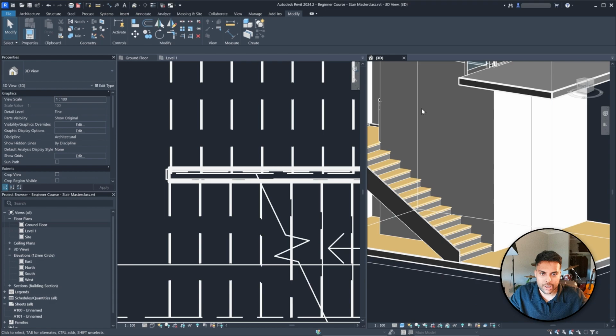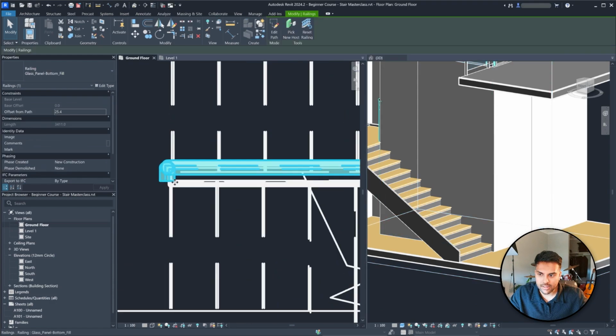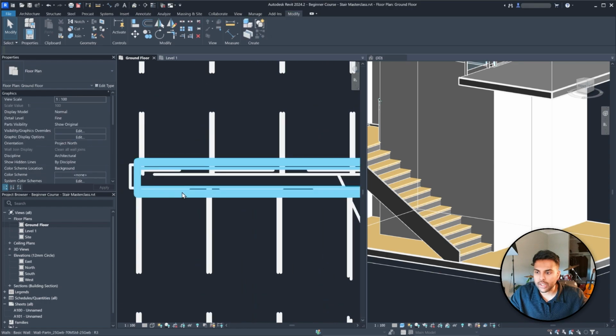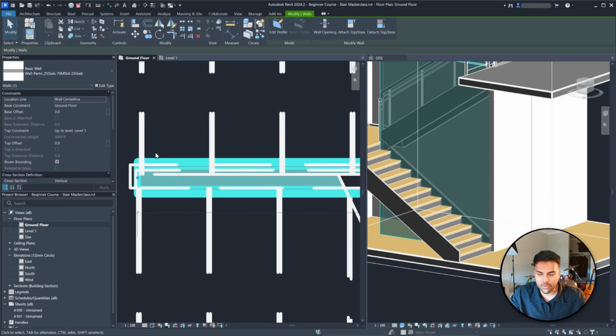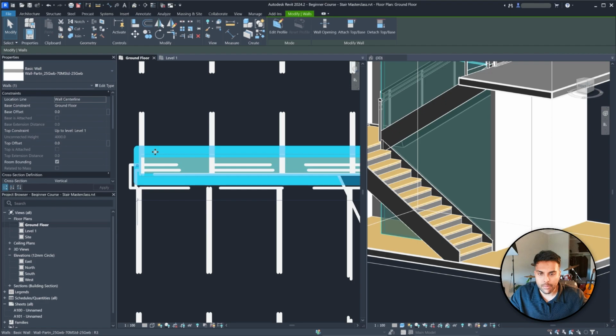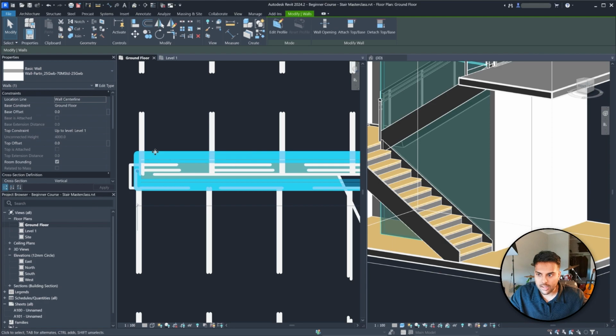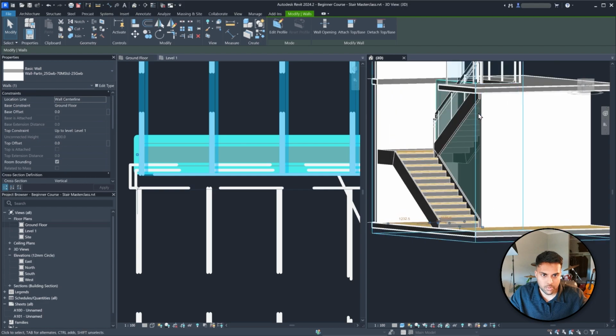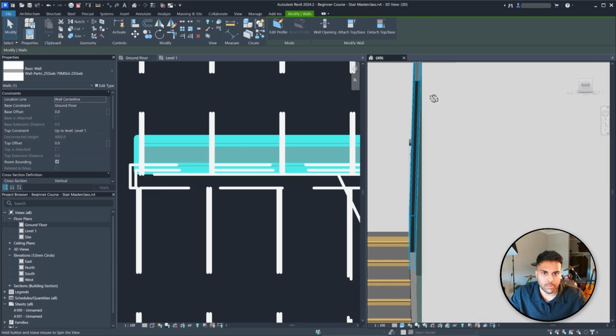You can't see any of the right supports. So what we're going to do is take that wall and keep moving it up until we can see both right supports. As you can see, you started seeing both right supports right about there, okay? But you want to extend it all the way so that we're engulfing both of the supports.